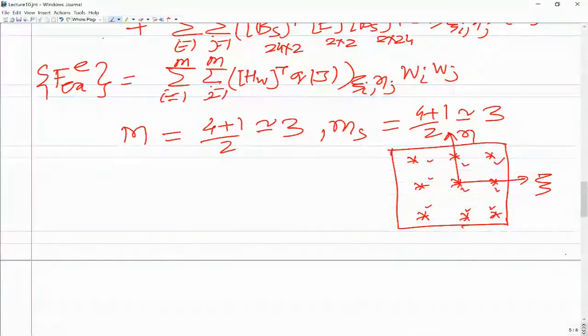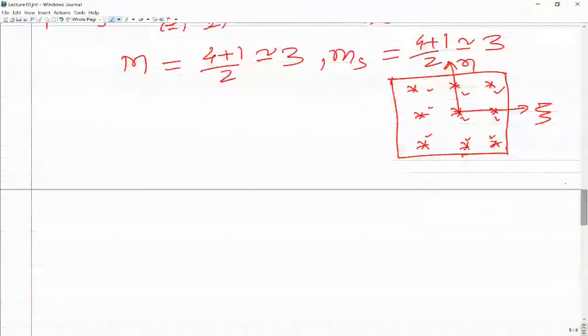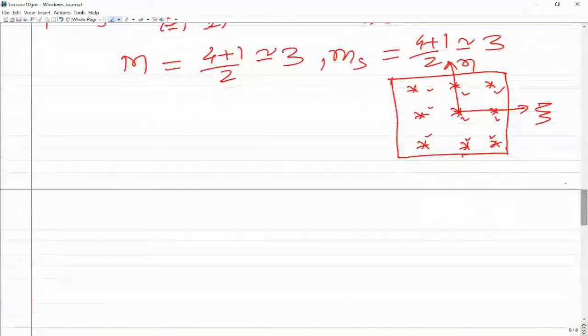Now, we talked about the shear deformable plate bending element, 4 noded element, 8 noded element. Similarly, you can formulate a 9 noded element. That means having mid side nodes and also the center node. That would be a 9 noded element. You can see how to get the shape functions. The same logic I used for the 8 noded element gives you the shape functions for the 9 noded element. So you can do that, and I'm not discussing that.